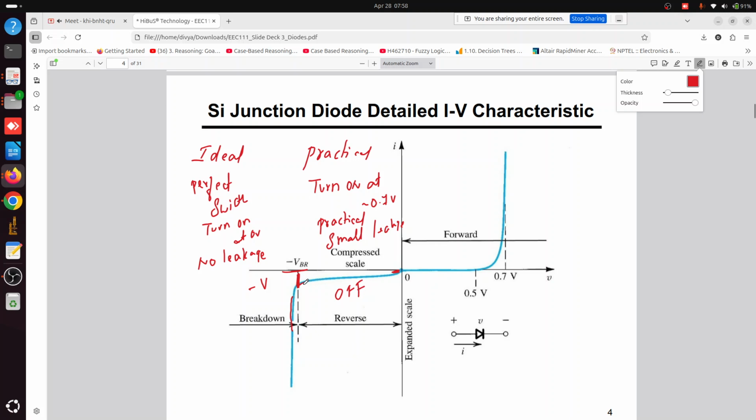Yeah, generally for negative voltage, you will have only a very small amount of current. That's leakage current, very small, close to zero initially. But when you try to increase this negative voltage, when it reaches this point, that is the breakdown voltage region, what is going to happen? Current is going to increase very rapidly, and this is called breakdown. Did you understand? This is called breakdown, right?